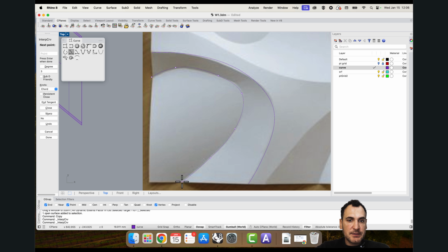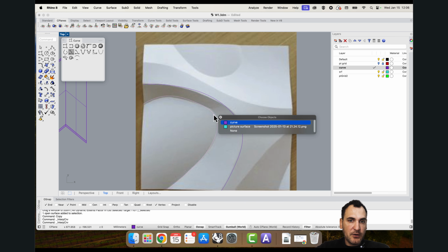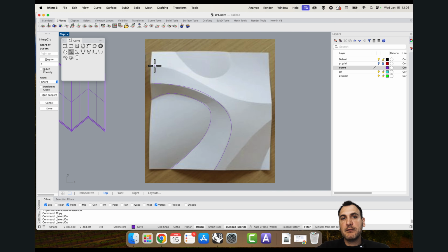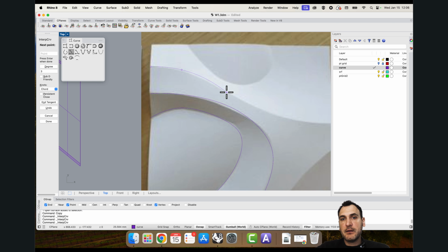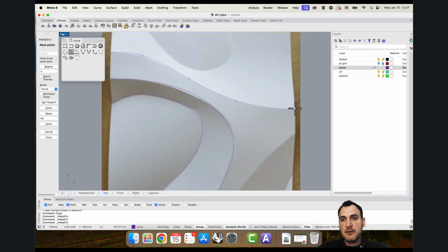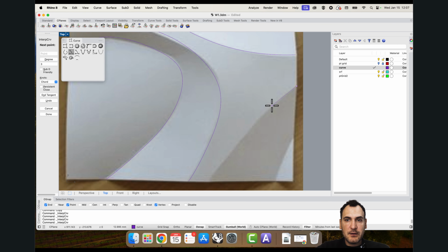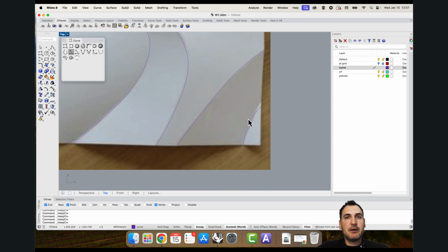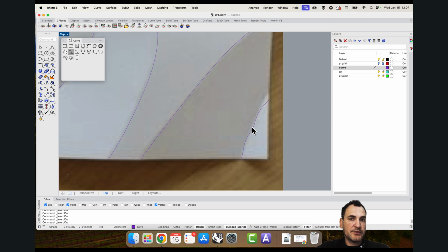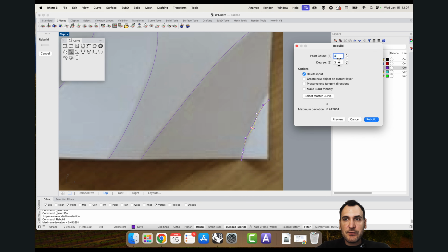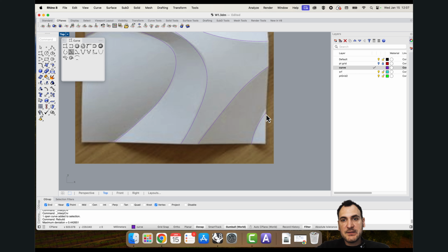And for some points, you might be slightly off, and what you can do is come back in and modify your control vertices. But you should be doing this with minimal information. So I wouldn't recommend putting, let's say, 10 points here, because then you will lose the curvature or the smoothness of the curve. So you need to rebuild these into simpler curves, basically.